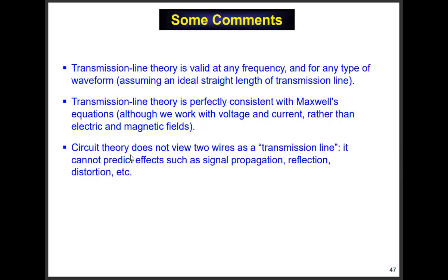So on a circuit board operating at 3 gigahertz, you really have to think that for the microstrip line coming out of this processor or whatever, going to this component, there's a wave, right? There's a signal going out of the generator, clock signal, whatever it is, going down the line to reach this component. That's how you have to think, right? You can't think in terms of circuit theory. That's not valid anymore. Even for modern computers, everything is a wave now going on that circuit board, right? That's going to go down the line, it might reflect. If there's a mismatch between the load and the Z0, energy might come back. There might be multiple bounces. We'll do that kind of problem before too long.